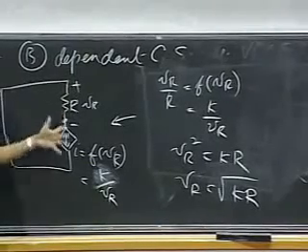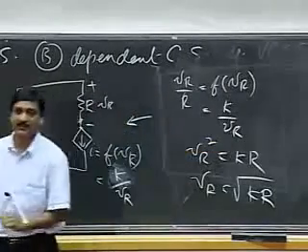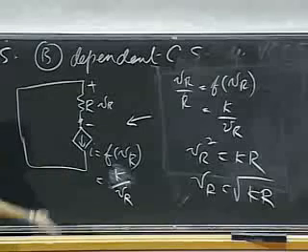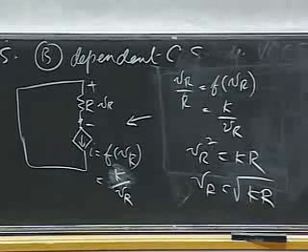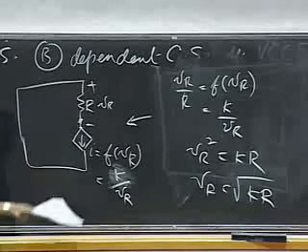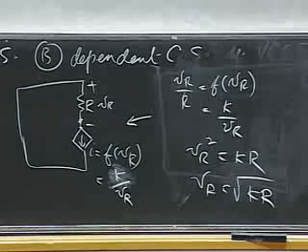And when I have to figure out the current here, I simply reflect the fact that it depends on VR, like so, and I just go and solve the circuit. Remember, the workhorse of the circuit industry, the node method. When in doubt, apply it. Okay, it simply works. And notice this is a nonlinear circuit. Okay, the dependence is nonlinear, and I get the response like so.